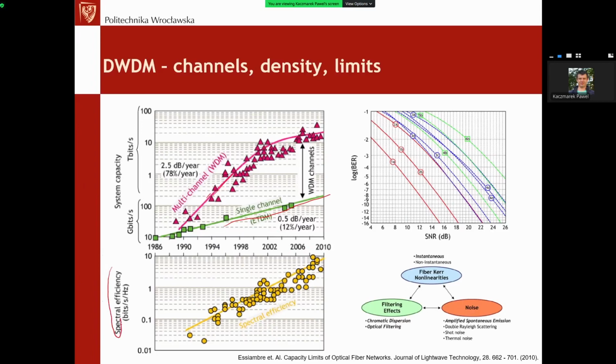But there is also an additional parameter and additional development in so-called spectral efficiency. Right before, I told you we can say we have 1 bit per second per 1 hertz of bandwidth used. It isn't fully true because, depending on the modulation scheme and other things, the spectral efficiency can be quite different. For these old telecommunication systems, you can see the spectral efficiency was much lower, and the spectrum used for 1 bit transmission was quite big. Right now, we are over the possibility of having more than 10 bits per 1 hertz of bandwidth used,